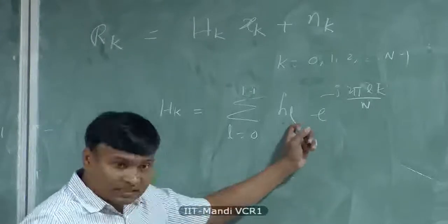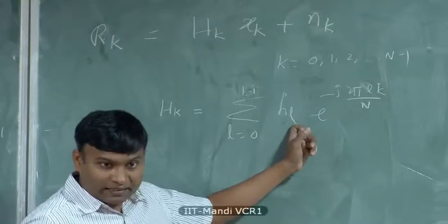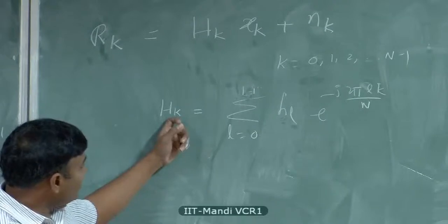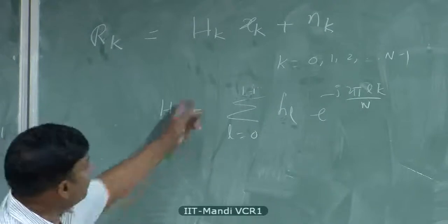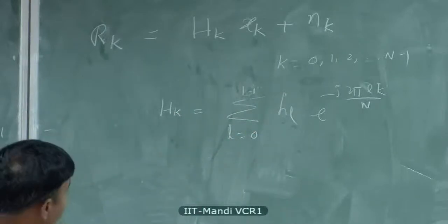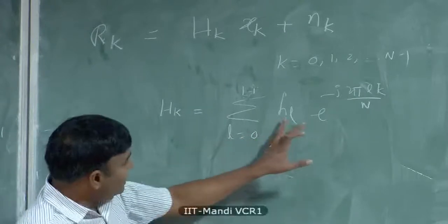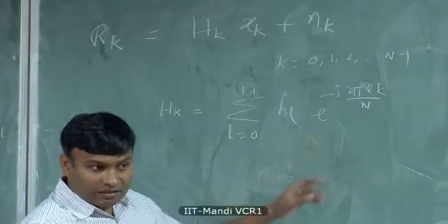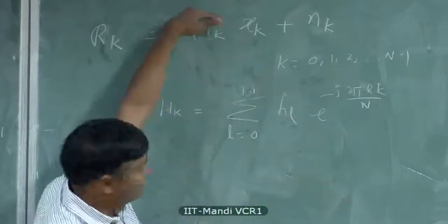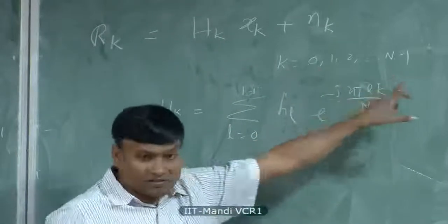This is what the receiver observes, h[l], in time domain. And after taking the DFT, H_k is what the modulation symbol experiences. But you can already see that if the channel h[l] is a single tap, H_k will be flat, right? And the gain would be the same for all subcarriers. What are the subcarriers? Here k from 0 to N minus 1 are the subcarriers.